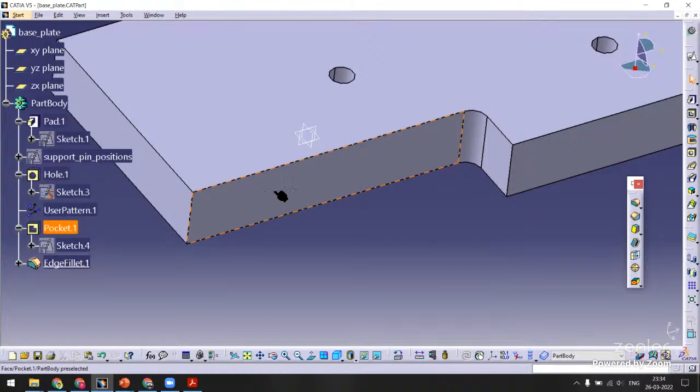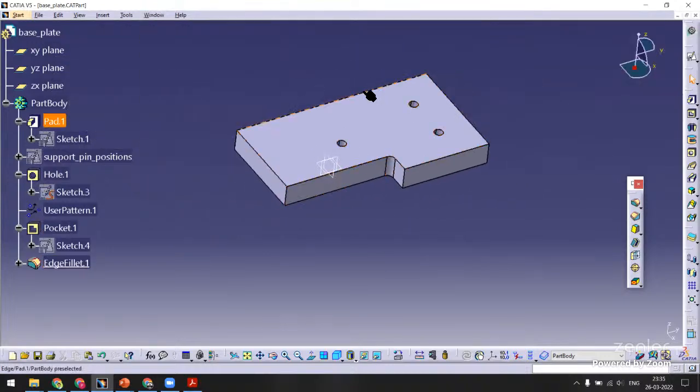And then the milling machine cutter is circular in shape. So I'm going to put a 5 mm radius so that we can do this with a 10 dia milling cutter. You can't keep this sharp. If you keep it sharp, it's not that we can't make that sharp edge, but it will become very costly to make that sharp edge. And then it is insignificant. Why do I need a sharp edge? It has got no functional requirement to be sharp. So it is always better to provide some radius, slightly higher value, so that it's easy for manufacturing.